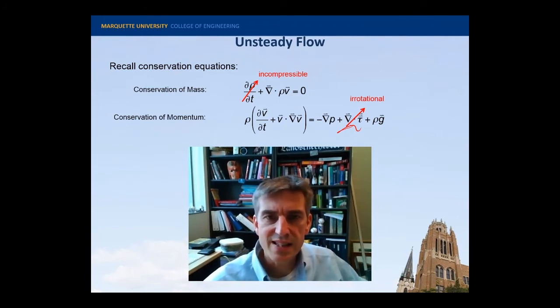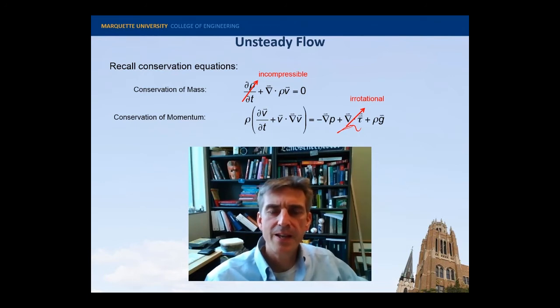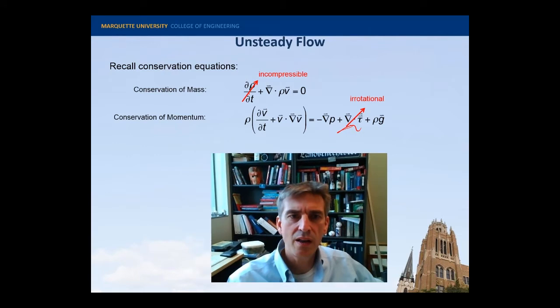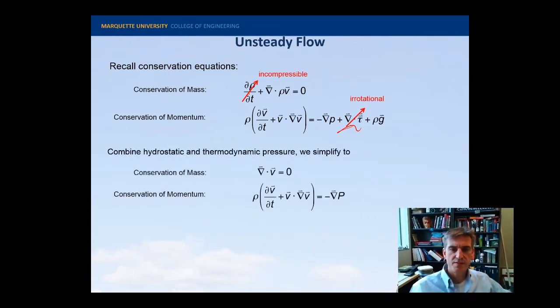So it's steady in time. Then we are left with this conservation of mass, del dot v. I've divided out the rho here, and since we're assuming it's incompressible, it's constant, so I can pull it out of the operator del dot, and then I can divide through because rho is not 0, and so I'm left with just del dot v.